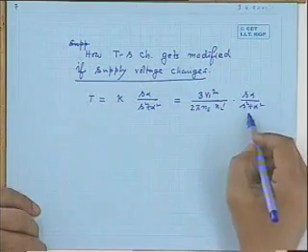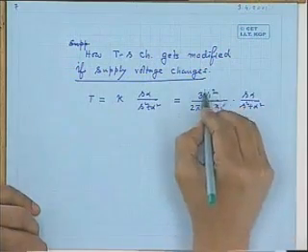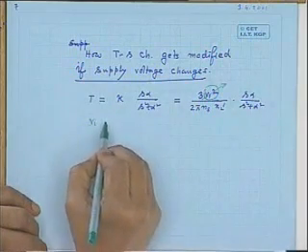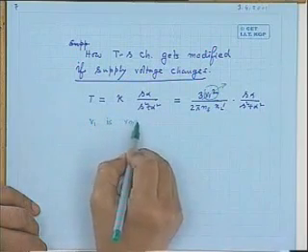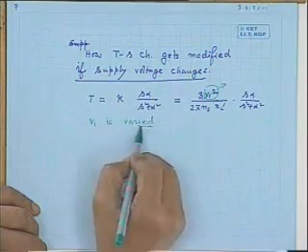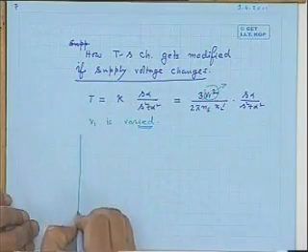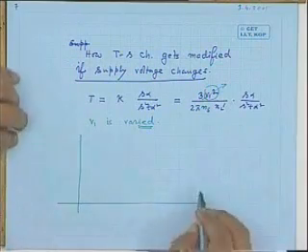So in this case, we are not changing alpha. Alpha is R2 dashed by X2 dashed. So alpha is constant. Only V1 is the thing I am trying to vary. V1 is varied, the applied voltage to the stator is varied. Then how will the torque slip characteristics change?